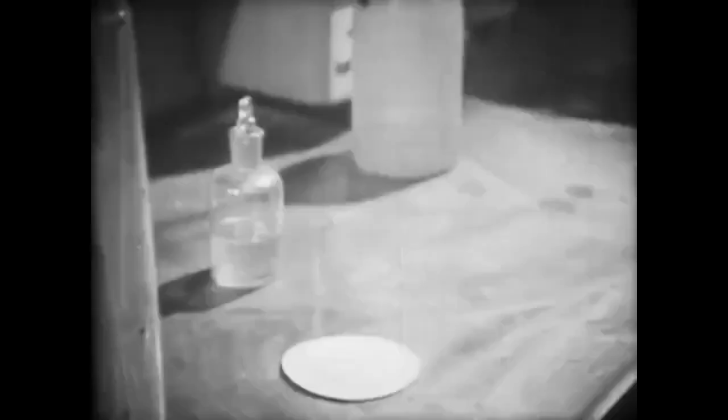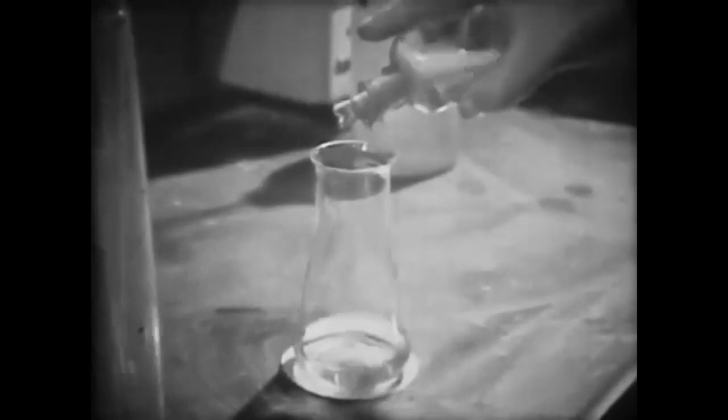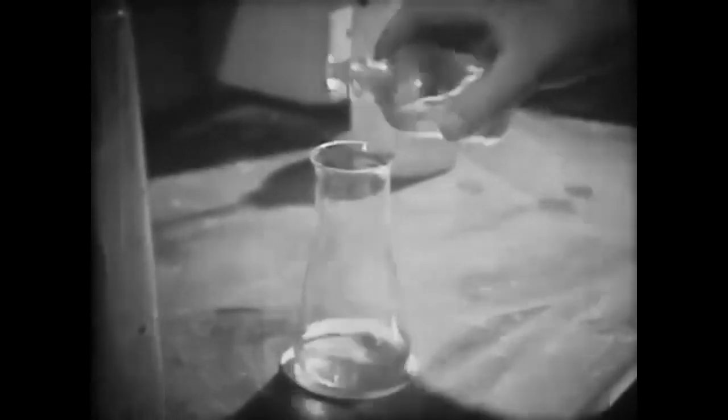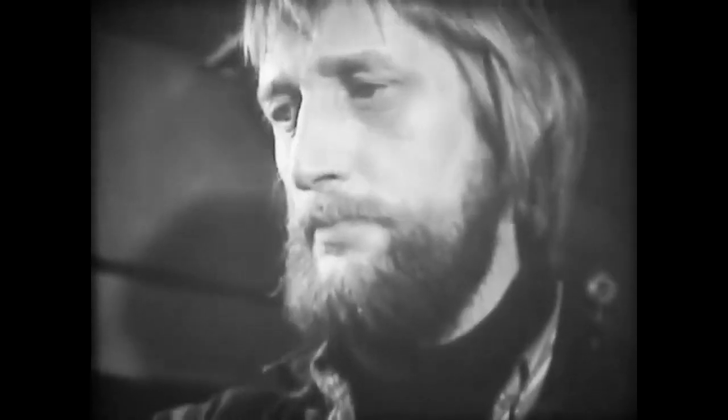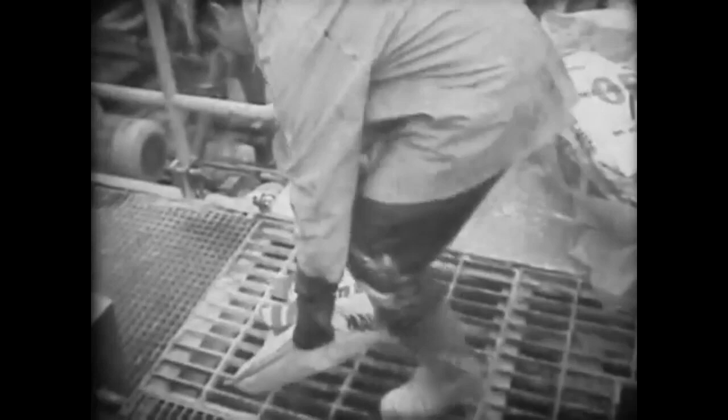Frequent checks are also made for any changes in the chemical composition. If we were to hit a layer of salt, for instance, we could be in deep trouble. The mud would cease to do its job, causing the hole to collapse and prevent drilling. We might have to replace the mud with a new supply of an entirely different composition to neutralize the salt.